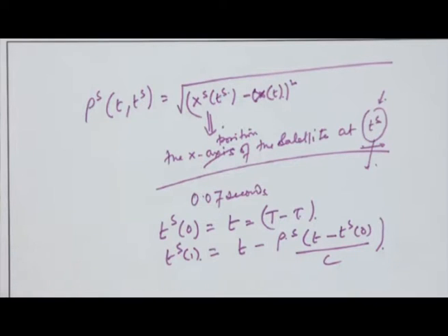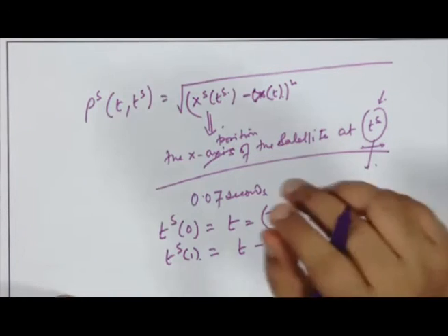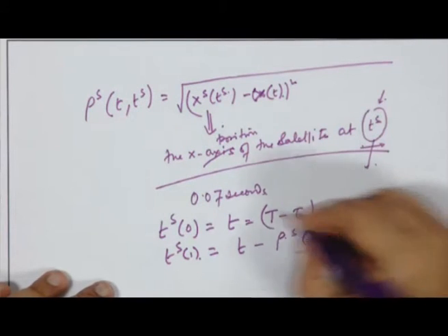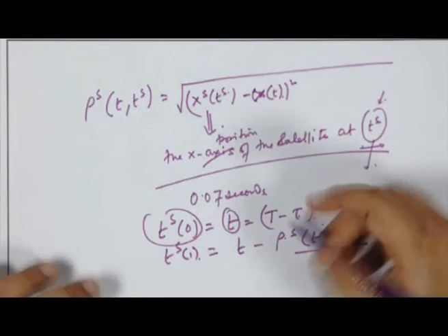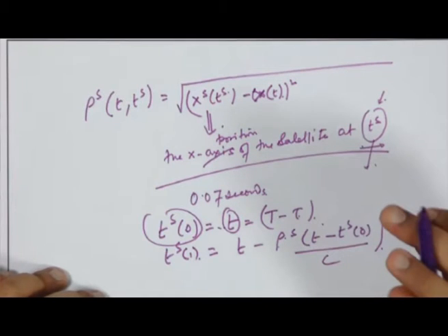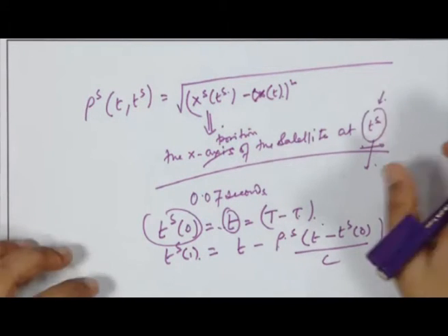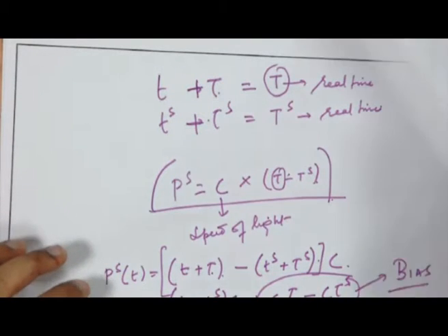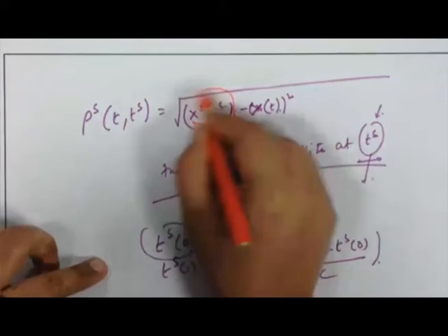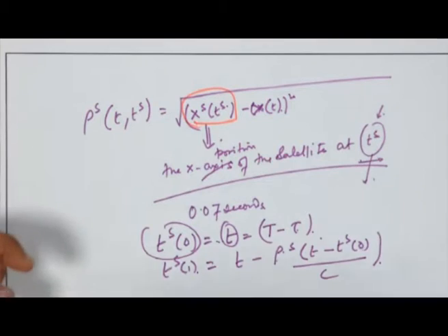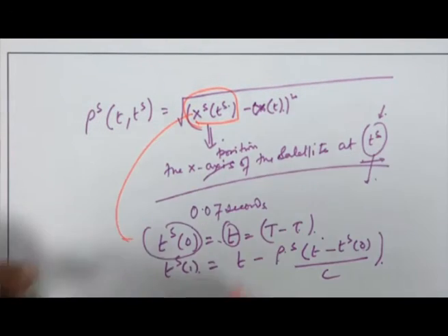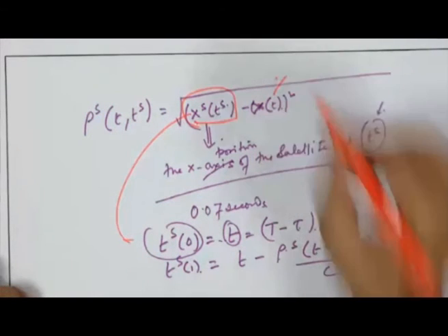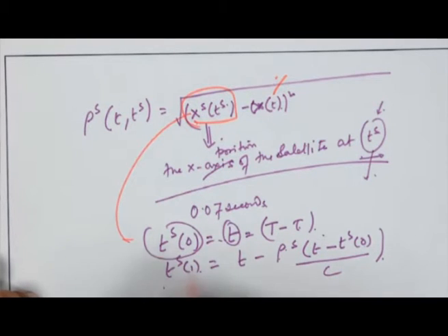So what is Ts1? I am saying that it cannot be so small. First these two are the same time, and taking this time I am calculating the distance. If I go back to the previous question, I have to get the satellite position at Ts, which is not known. So I forget that I don't know and take Ts as T, and then do an iteration. Initially I took Ts as T, but Ts cannot be T.